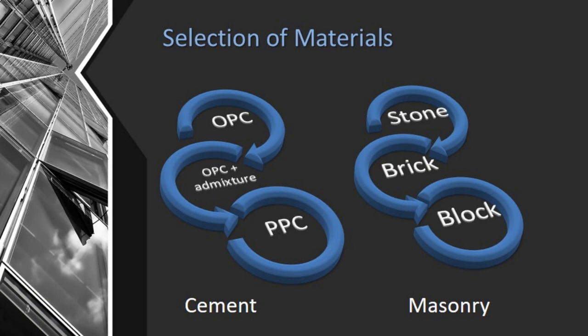So my suggestion for the mix designers and consultants watching this webinar is that you should not always take 33 MPa as the strength of the cement during your mix design. You should always check the detailed sheet provided with every lot of cement. When you receive the cement on your site, you can ask for the technical sheet, the TS we usually call it. The technical sheet will tell you the strength the cement achieves at 28 days or at a particular point of time. According to that, you should design your concrete mix. So that is the thing I need to discuss here.